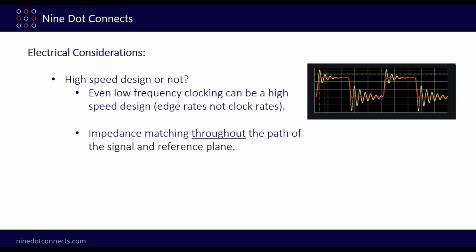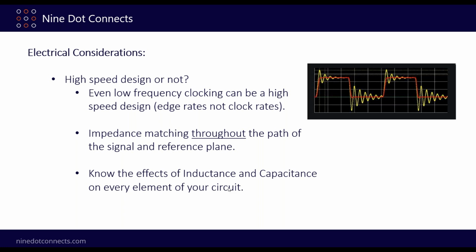Impedance matching throughout the path of the signal. Sometimes we think about the output impedance of the driver, or the input impedance of the receiver, or even the stack up, having the path be matched impedance. But we have to remember that throughout the path, the signal has to be matched. So looking at the signal and reference plane is very, very important. So always keep that in mind.